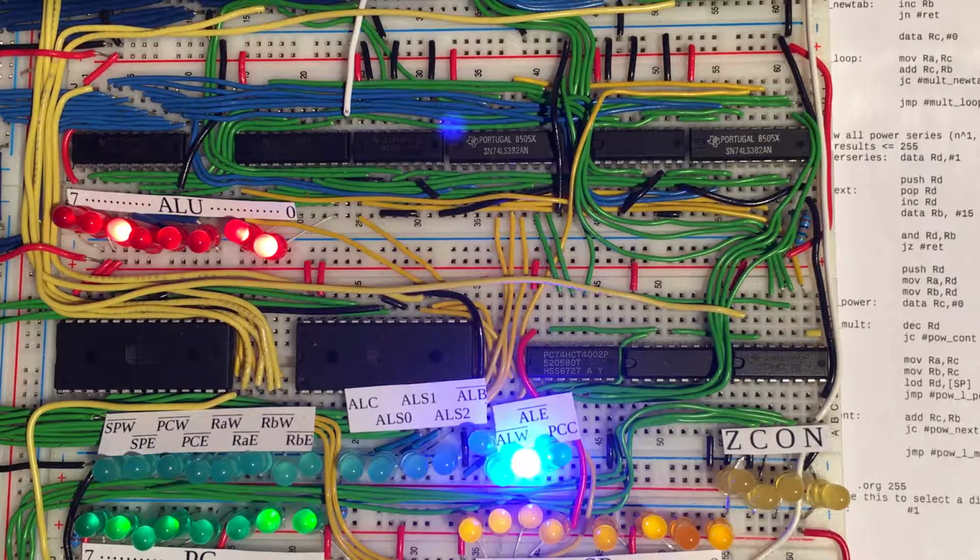So that's a first look at the way we've implemented the ALU. So we've seen what instructions we want to support. So we have arithmetic instructions, add and subtract, both with or without taking into account the carry. We have, of course, all of the logical instructions, the and, or, not, and the exclusive or. And then we have 2 single operand instructions, increase and decrease. And we can use those for any of the 4 general purpose registers, but we can also use it on the stack when we're implementing the pop and the push instructions.